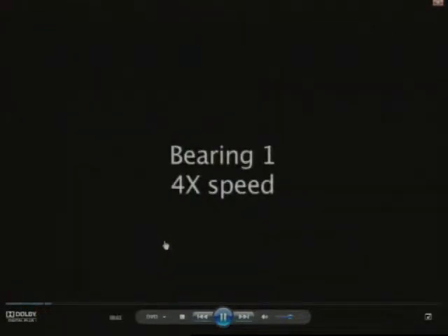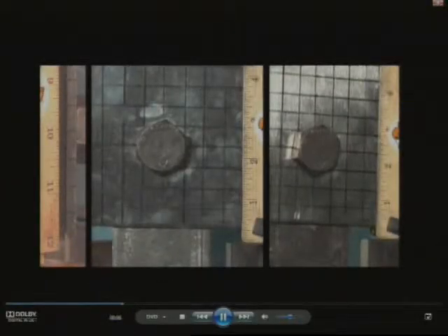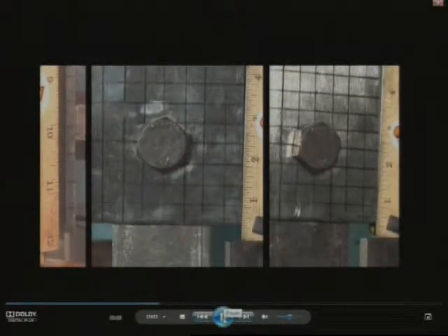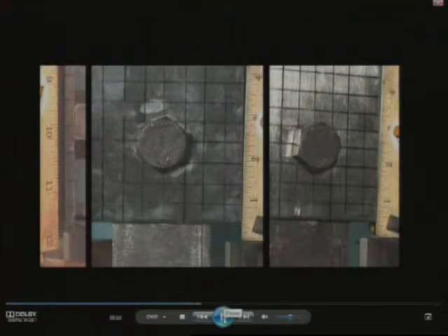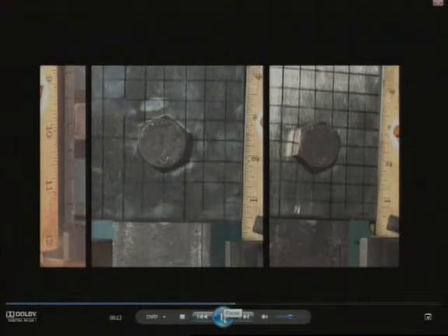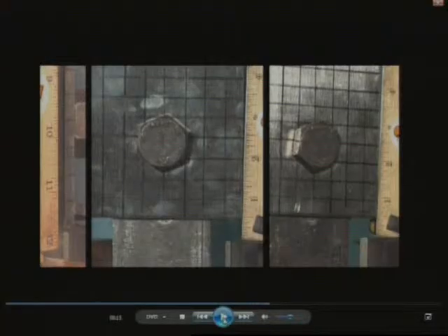What's going on here is we're actually starting to load, and eventually we snap the head off the bolt. As we load, I'll pause it whenever a major event occurs. Okay, so we can already see this bolt's just chopping right through this steel. It's just cutting right through it. It's bearing. There's localized buckling going on right here on this bottom surface that we can't see very well.